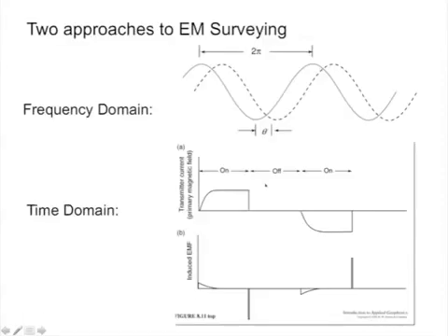So Ampere's law. All right, so we have to put in some kind of change to a magnetic field into the Earth, and then we'll get eddy currents. We'll get resistance to the changing magnetic field. We'll get Ampere's effects, and those are going to allow us to get some measurement of the conductivity of the material in the ground, the resistivity of the material in the ground. So there are two approaches. Okay, there's frequency domain magnetic EM surveying and time domain EM surveying.